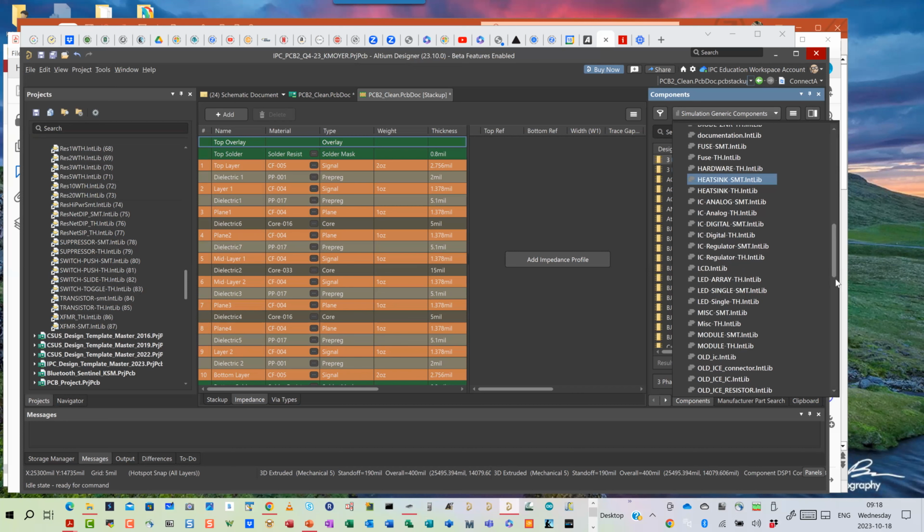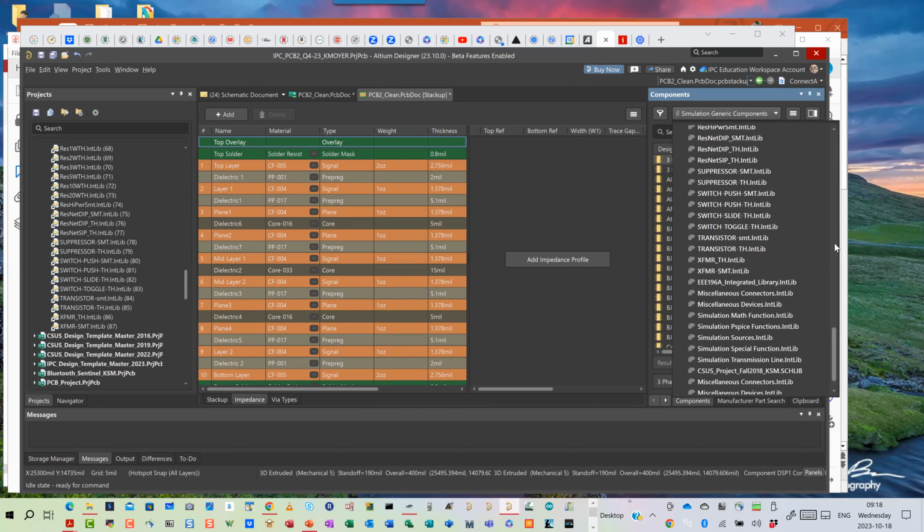And then even down here, I'd get even more granular. We had some standard resistor sizes we used. So I'd have my 0.1 watt through holes, or my surface mounts here, right? So there was my 0603s, my 0402s. So I said, okay, you want a 0603 resistor? Here's my 0603 resistor library. So it's just a matter of creating the library.